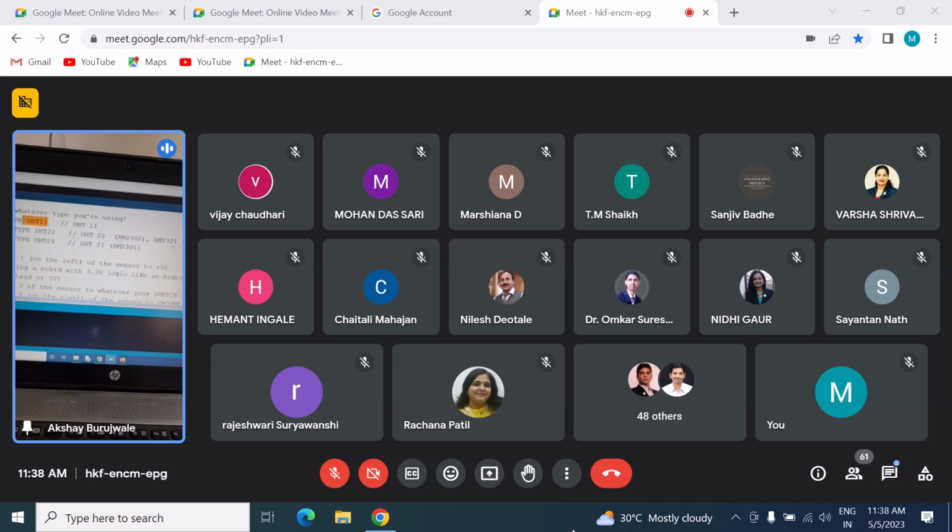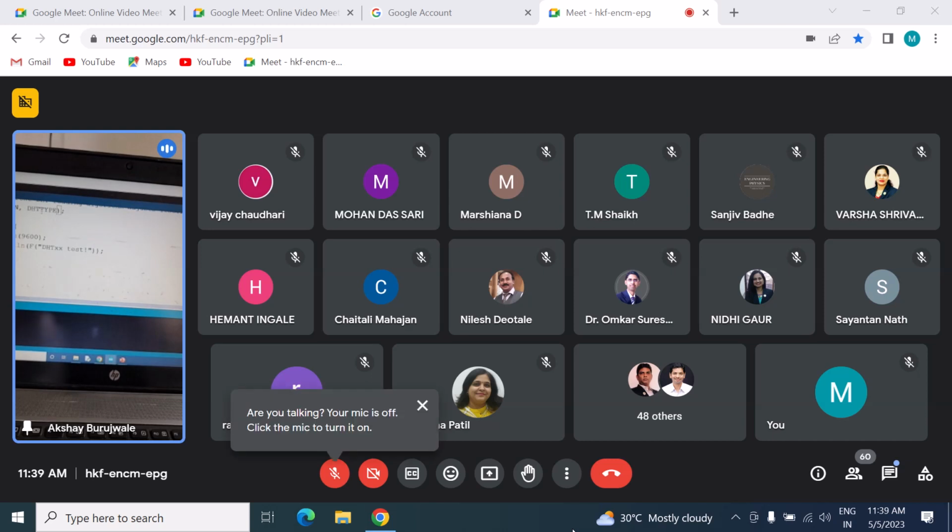There are a number of sensors: DHT11, DHT22, DHT21. They have made this code for the 22, so I am changing that setting and opening my DHT11. Going to the bottom, you can see it here. DHT is a class, and it is creating an object with the DHT pin and DHT type. That means which pin the DHT is connected to, which we have changed to 5, and the DHT type, that means 22 or 11. We have changed these two settings, and that's why it is getting updated.